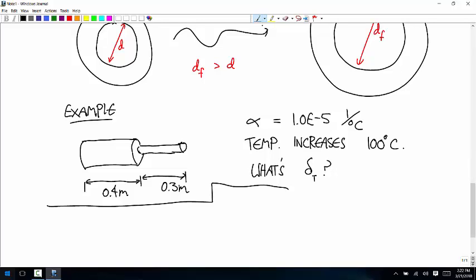And it's that mismatch in sizes that causes it to crack. And so the reason beakers are made out of Pyrex glass is that Pyrex is made specifically to have a much lower coefficient of thermal expansion. So if you heat a corner of Pyrex up to the same temperature, it's less likely to crack because of the mismatch in size with the surroundings.